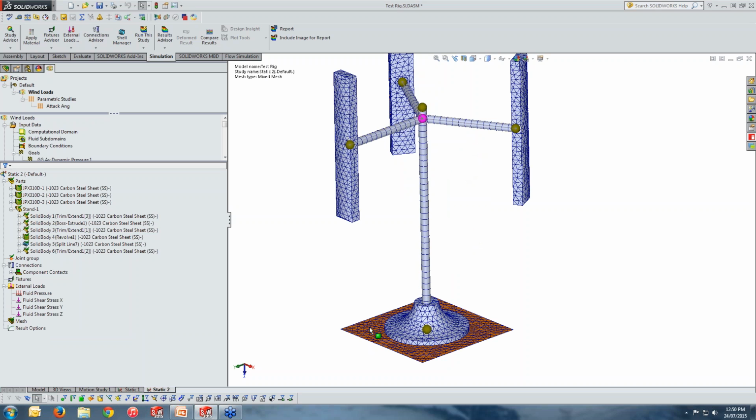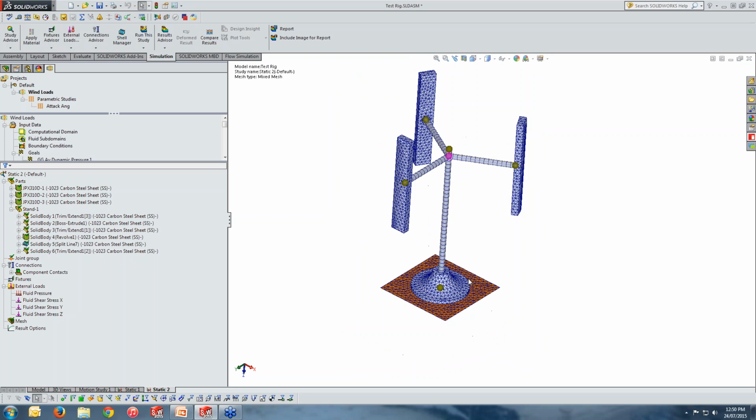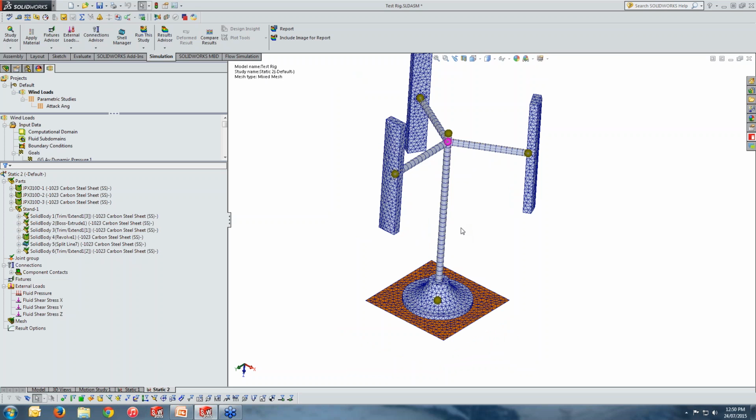Again, like from the flow side, here we have a very important topic of having a very good mesh to converge the answer and capture all important effects. Well, that would be a very separate topic, and we are not going through this, and we are accepting everything here. But one thing for sure, our mesh should be perfect, meaning optimized, not very coarse, not very fine, and capturing all the important events happening in our structure.